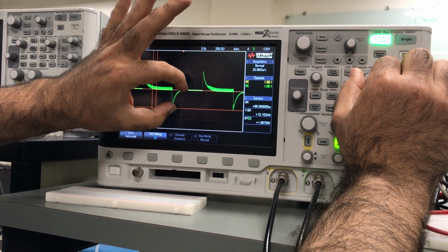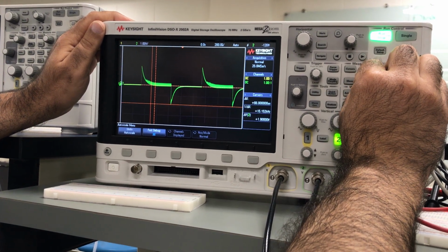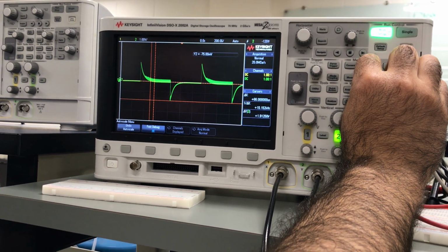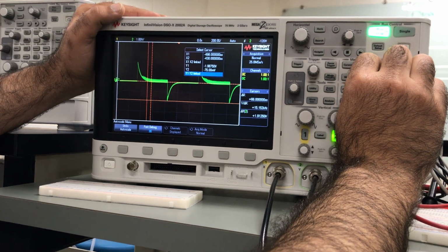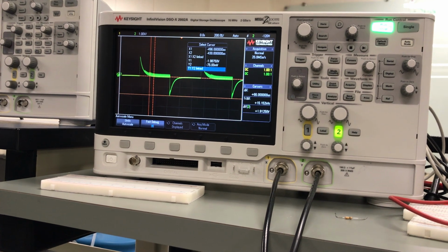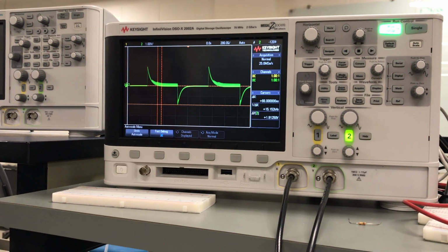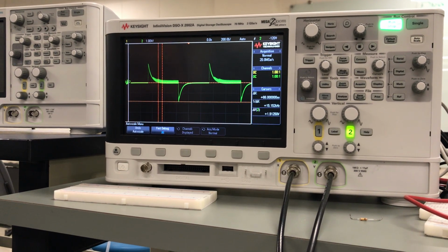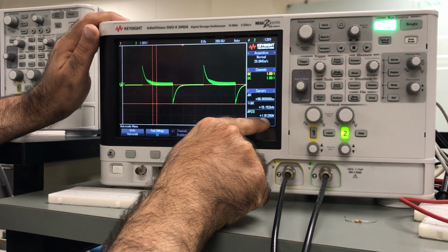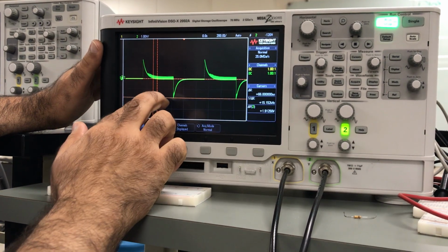So I would like to measure the height from here to there, which is approximately 1.9 something, which is okay. Then I will try to calculate 63.2% of this height. If you calculate it, it will give you delta y, which is equal to 1.219. I'm going to take 63.2% to find where the time constant, delta x, is.